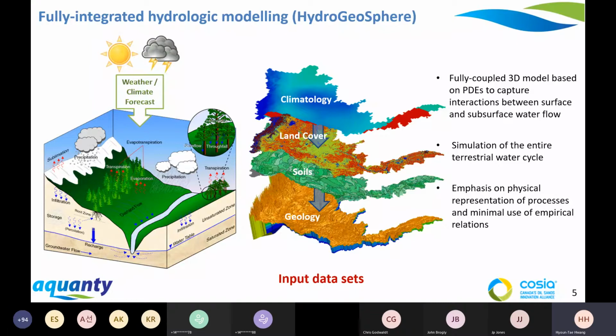Using these climate data sets, you can simulate snowmelt and snow accumulation, freezing and thawing, evapotranspiration, and all types of surface water flow conditions. In the subsurface domain, you can simulate infiltration through the vadose zone and saturated flow under complex conditions such as fractured media, tunneling, tile drains, etc.